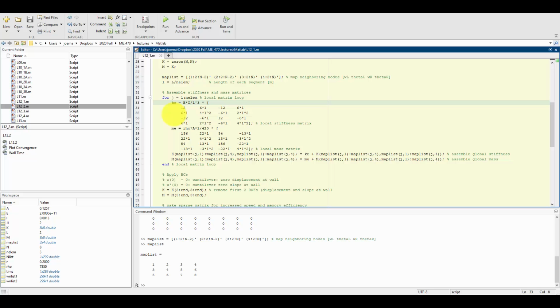Again, this particular shape function is good if we are working in materials that are linearly elastic and we're staying below the yield limit, we're staying in that linear elastic region. So even for a different type of material, or if we're going into plastic deformation, in that case we might want to use a different shape function, which is then going to change our local mass and stiffness matrices.